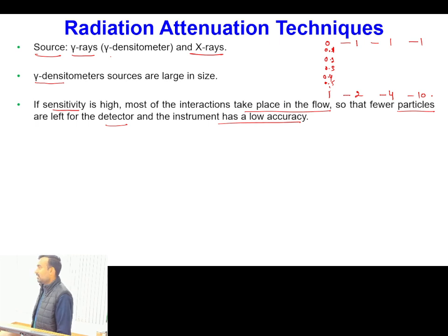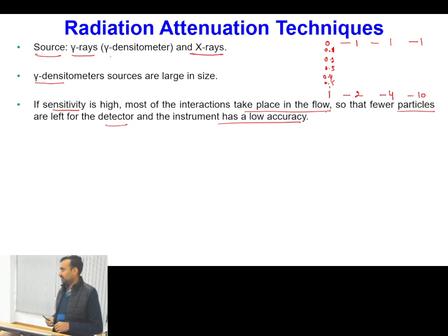The last one. Wherever we have a large range of output signal available, whenever I do interpolation, I can get the void fraction data in fractions also, between these numbers, almost a continuous variation of the void fraction. But if my signal strength is very small, say varying from 1 to 2 only, then whatever interpolation I do, there will be many chances of errors in comparison to the actual signal output, and there will be inaccuracies in the measurement. Is this clear?